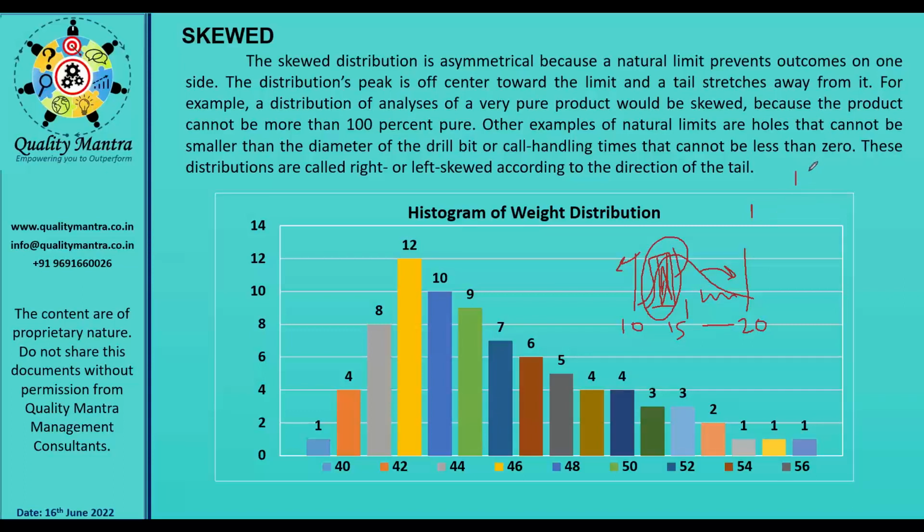Normally the PPK of 1.67 is demanded by the customers from their suppliers. I don't know whether your organization is following this or not, but many of the customers are now asking the supplier to maintain the CPK of 1.67. So just supplying the data within the specification limit is not enough.